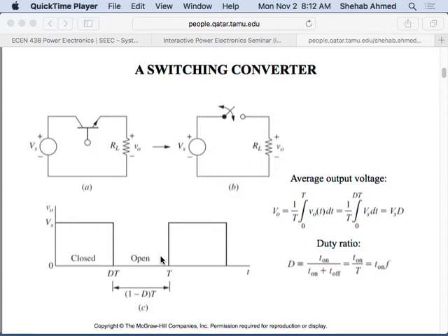Then it's okay, right? Motors, for example, are driven by inverters. They are power electronic devices, and 95% to 99% of the time, there is no output filter at the output of an inverter. And we will see that the inverter output is a pulsed waveform like this, right? Why is that the case?